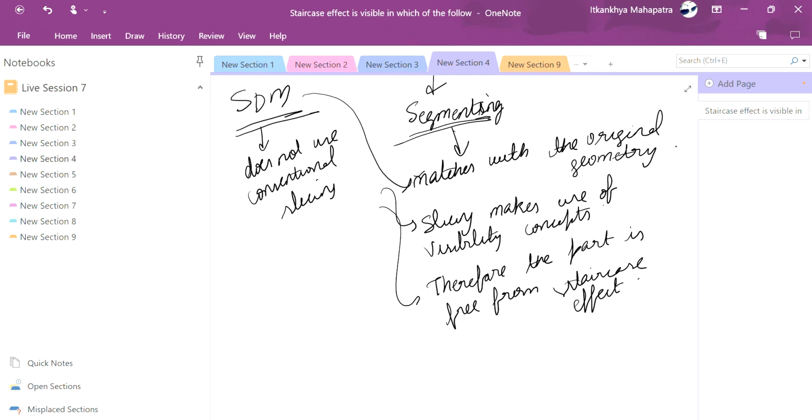So in this slicing software, we provide various parameters. The parameters can be whether you want to give any supports, any additional layers such as raft or brim, what percentage of density you want, how much each layer size, what are the starting layer sizes, what are the ending layer sizes, and various other parameters.